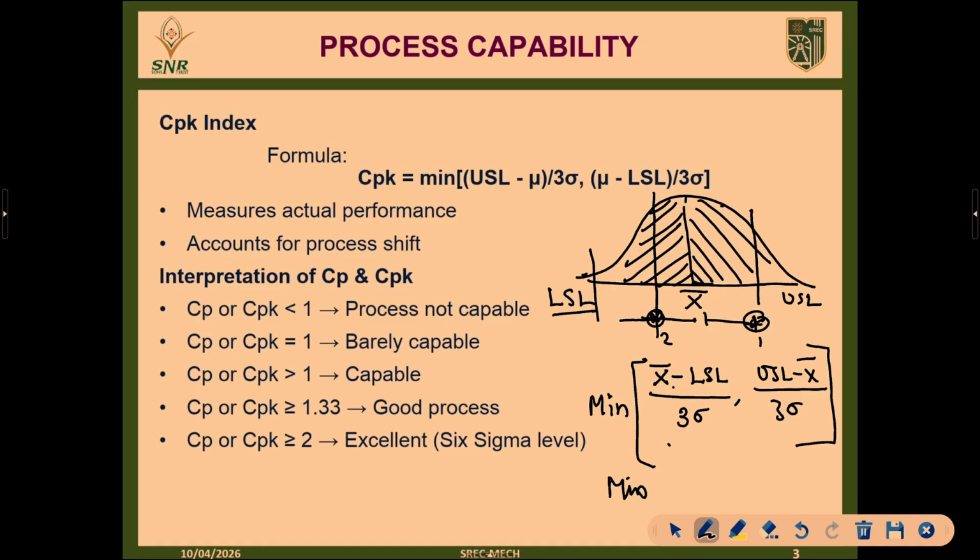So this is how we have to calculate the process capability and the process capability index, two metrics. Based on that, we can assess whether the process is capable or not in producing quality products as per the customer's specification. Now we have calculated process capability and process capability index. Which number is good, which number will represent the quality of the process or ability of the process?